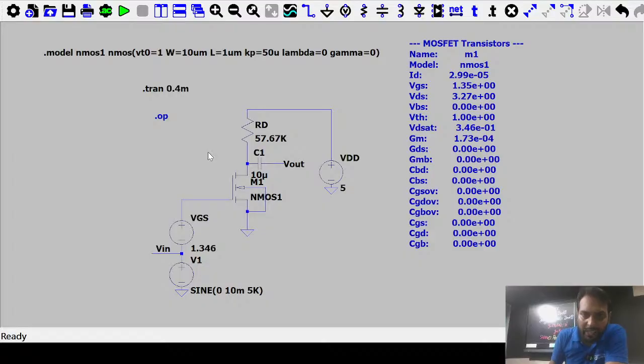So you are just writing the SPICE directive. You can take the SPICE directive from the analog lib in LTspice. You can search it. What is the SPICE directive to determine the gain? How can you determine it? So this is the parameter: .measure gain param V out by V in. So you can use this, and you can place it here.